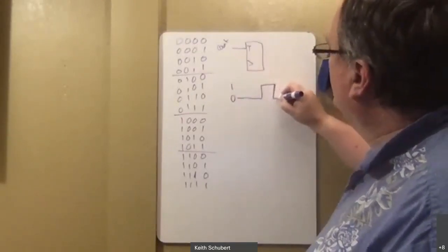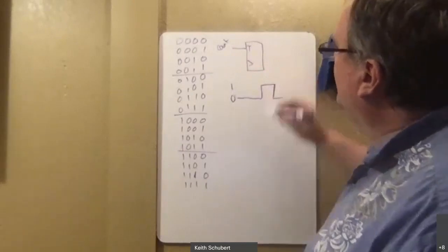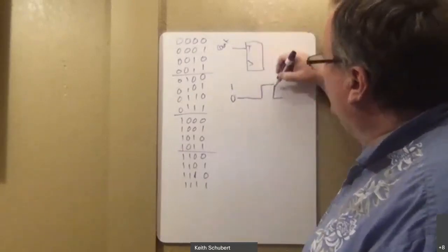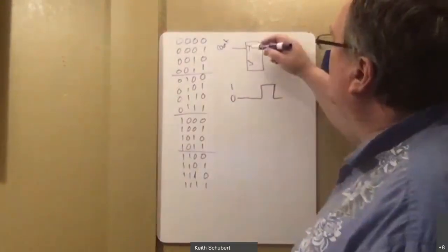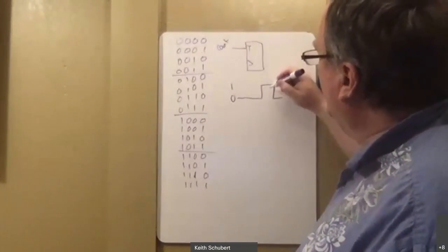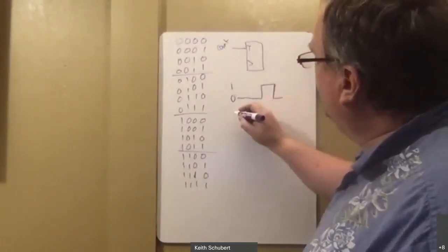You give me a count pulse. Now, the thing you have to be careful with this count pulse is if you hold it for a while, you'll get a bunch of counts. As soon as this is high, it will do a count. So you have to measure these off of our clock.